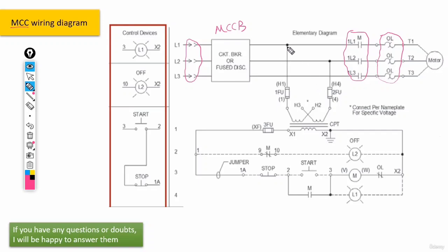Now guys, as we previously mentioned, we can use two of the three-phase lines like L1 and L2 for feeding the control circuit. We'll get an incoming voltage from these two lines, L1 and L2. Then here we have two fuses, but we can also use one. Then right after we have this transformer, a step-down transformer, which decreases the voltage for feeding the control circuit. All right, now as you can see, there's another fuse here. And then everything is connected to the control circuit.